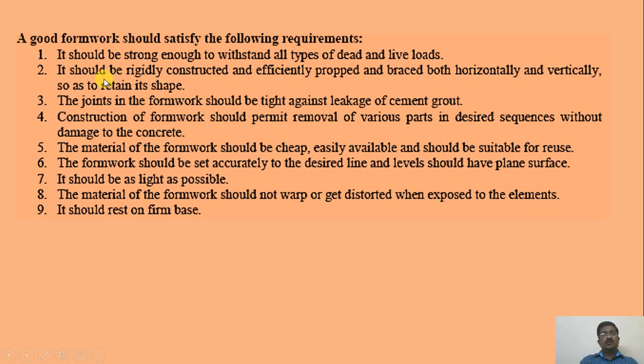A good formwork should satisfy the following requirements. It should be strong enough to withstand all types of dead and live loads. It should be rigidly constructed and efficiently propped and braced both horizontally and vertically so as to retain its shape.